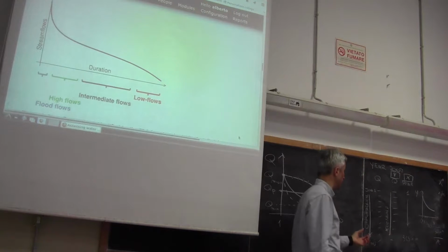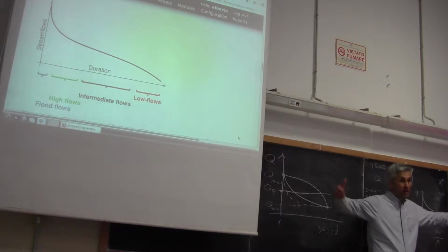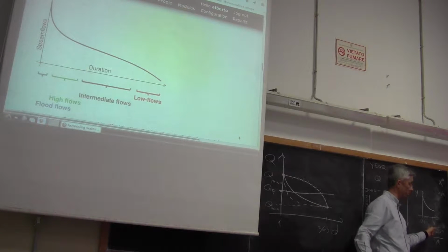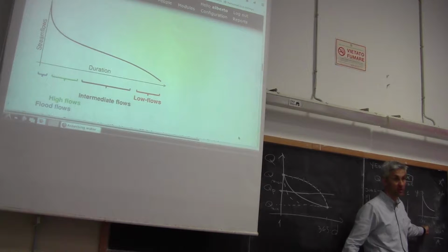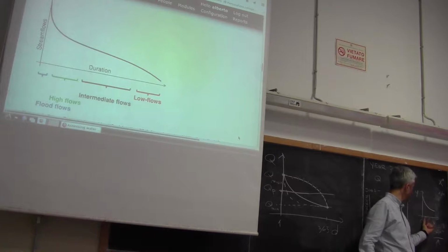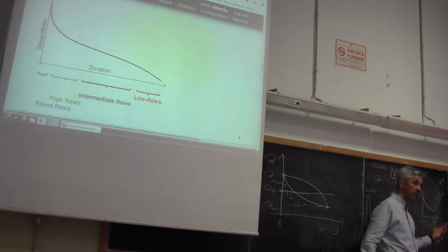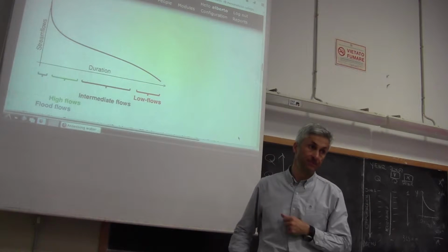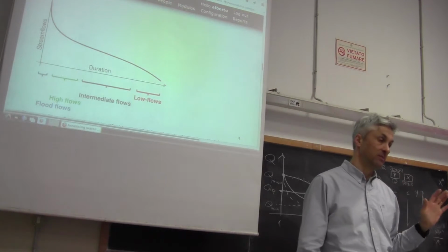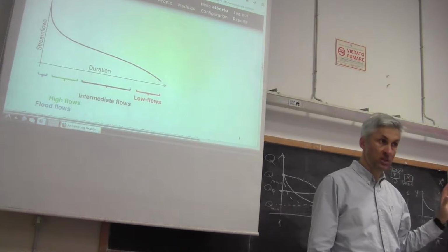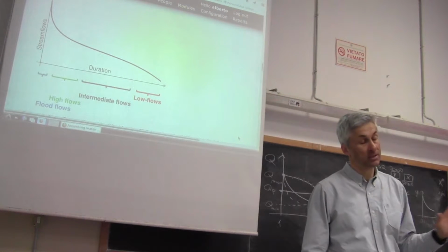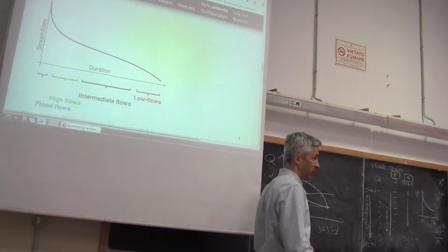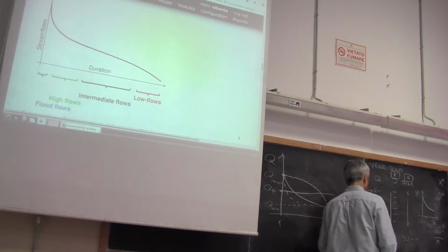Okay? If you have a flow duration curve that is based on a long observation period, and therefore you get the flow duration curve according to this second computation method defined up to a duration that is close to 0, then it may be representative of a flood. But still, I would keep the concept that the flow duration curve is not representative of floods. It's representative of high flows, low flows, river flow regime, but not floods.